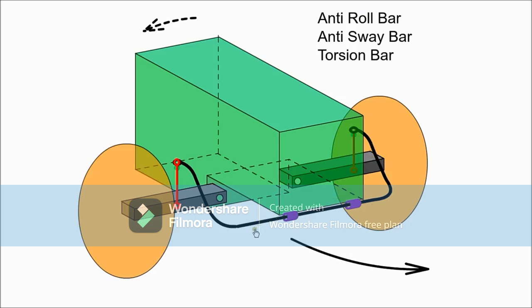Most cars have a front anti-roll bar, while sports cars may have one front and back. Obviously, if both sides of the suspension are connected together, we no longer have an independent system. A stiff bar reduces body roll, but too stiff can limit the operation of the independent suspension and cause the inside tyre to lift. Often a compromise is required.